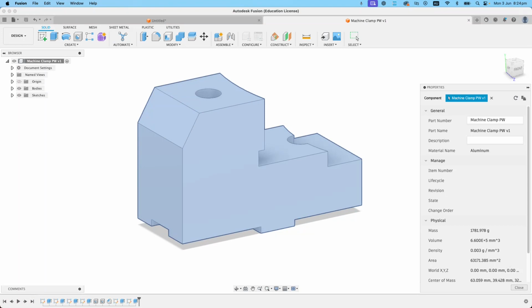Now, again, you guys may have come up with a workflow that is better than mine. I really just wanted to show you, don't overthink it. It's a rectangular block. Make some cuts, add a bit of material, make another cut, job done. Things that we've learned in here: making sure that you spend some time analyzing the drawing, just getting a plan together, a refresher of how to use the holes, particularly the counterbore holes there, and also the referencing using the art tools and those sorts of things.